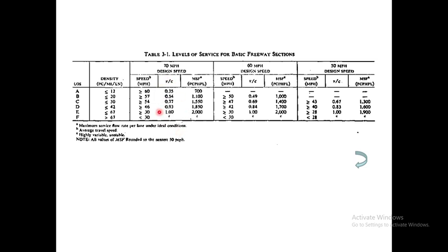This one would be used so frequently in many problems, okay? And we also have MSF, which stands for maximum service flow, right? So maximum service flow is obviously the maximum rate of the flow. For example, for level of service B, the maximum flow rate for a given highway is 1100.